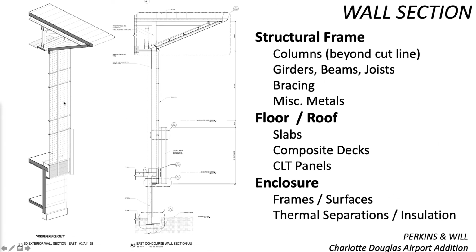In this case, the mullion is sort of spanning toward the interior, leaving a very flush facade on the outside. And so even the choice about where the mullions sit within the wall, do they sit to the outside and create shadows? Do they sit to the inside and create a kind of flush surface? Is an important connection that we would want to see in the wall section.